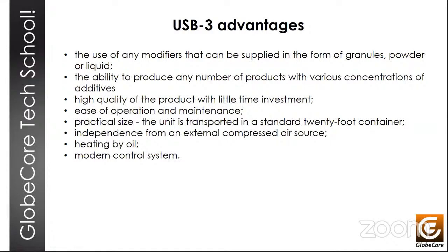The intermediate tank is designed for preliminary mixing of the polymer with bitumen, and it increases the contact time, the exposure time, I guess, of bitumen and polymer, which takes some of the load off the mill. And the tank is equipped with the high-speed agitator, the turbine mixer that I mentioned, which allows mixing the bitumen and polymer quite evenly. And it's safe to say that the modification process is pretty much finished in that turbine mixer, but the mill just adds better stability and homogenization of that product.